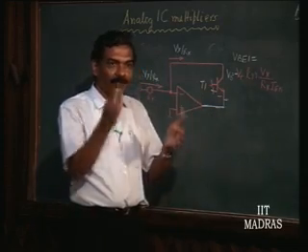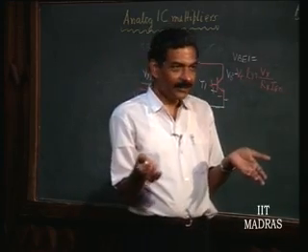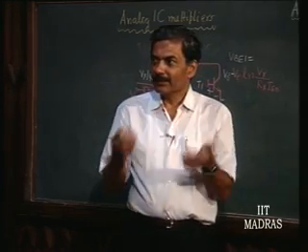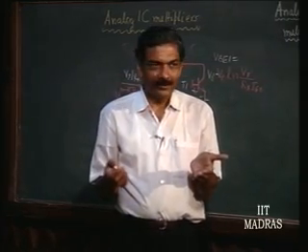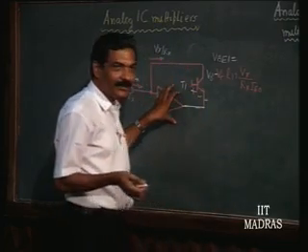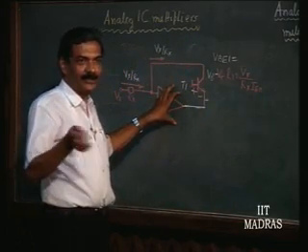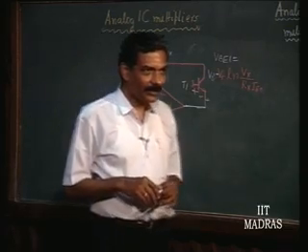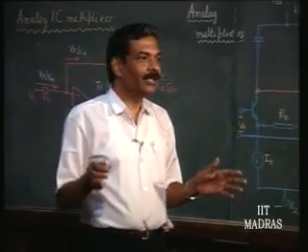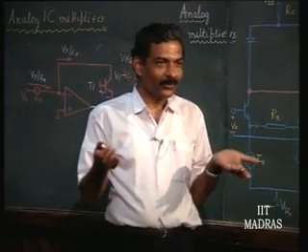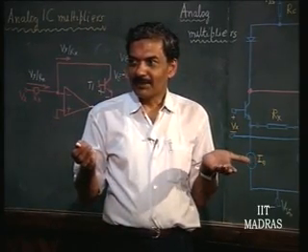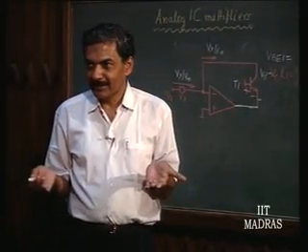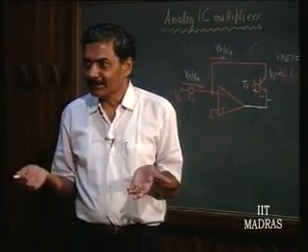That means, overall loop gain has increased in this negative feedback situation, right, from A to A into Gm into Rx. So, if your op amp has been designed with just unity gain kind of operation being satisfactory for frequency compensation, then it may fail, because now the open loop gain is more. That means, the frequency compensation capacitor might have to be further increased, because the open loop gain is increased.